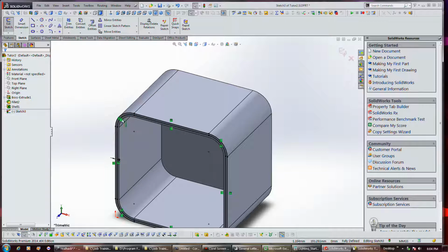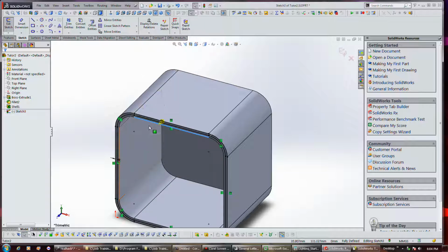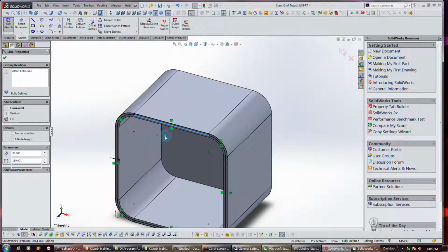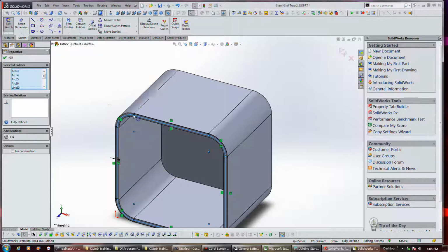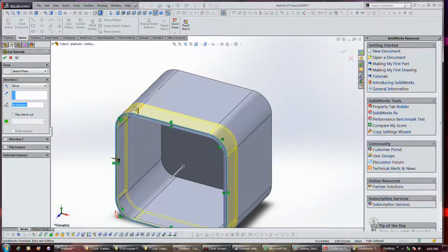Okay, so I created this. Remember, we're in the Extrude Cut command, so we're going to cut a lip, but we've got these 3 arcs here, or these 3 sets of lines here. So I guess I can't do that. But we do have these 3 sets of arcs here. We created this extruded offset. So anyway, if I close it, we're in the extruded cut, and we want to cut 20 millimeters.